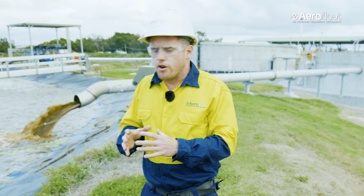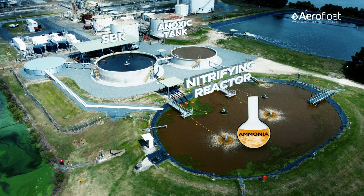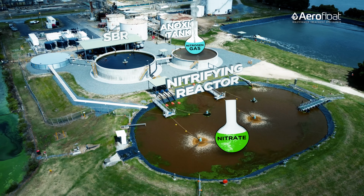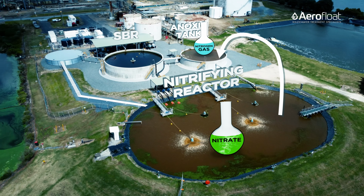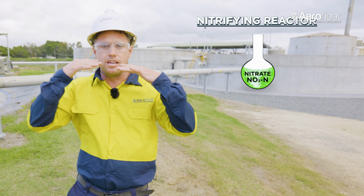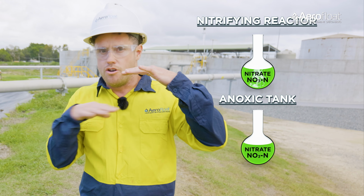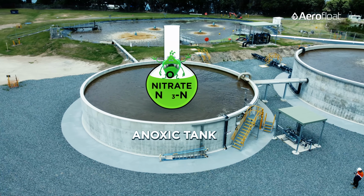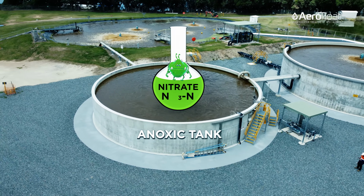So, we've converted our ammonia into nitrate. Now we need to reduce the nitrate to nitrogen gas. The way that happens is by pumping forward to our anoxic tank. So in the nitrifying reactor, we have dissolved oxygen. In the anoxic tank, we have no dissolved oxygen. And the organisms take their oxygen from the nitrate molecule.